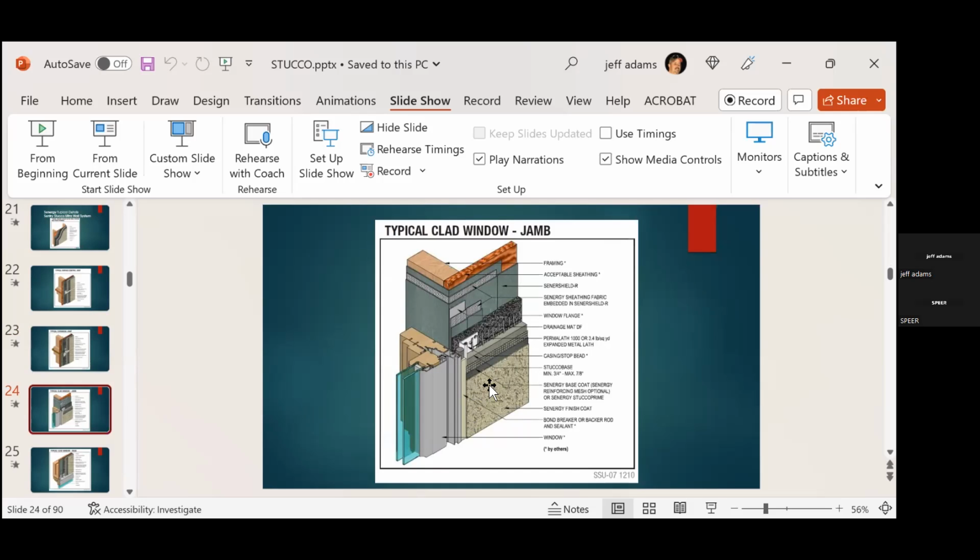You cannot do that. And when you start getting into aluminum windows, it creates a problem. With some of these vinyl windows, if it expands a bunch, it'll warp and distort the windows in some cases. Just not a good way to do it. It's not allowed. So it is required to have your plaster stopper, your casing bead, to create an embedded caulk joint and so forth. And that's what we have here that's creating that separation.